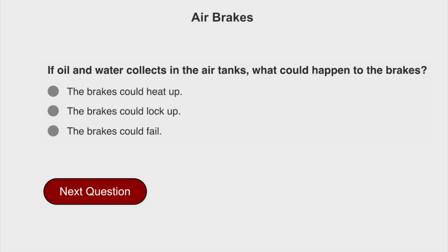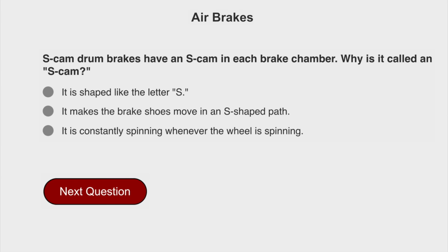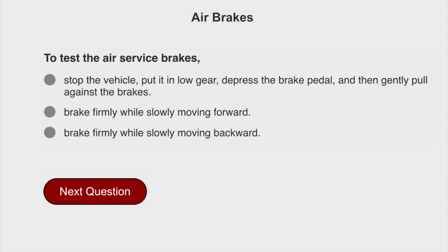If oil and water collect in the air tanks, what could happen to the brakes? The brakes could fail. S-cam drum brakes have an S-cam in each brake chamber. Why is it called an S-cam? It is shaped like the letter S. To test the air service brakes, brake firmly while slowly moving forward.